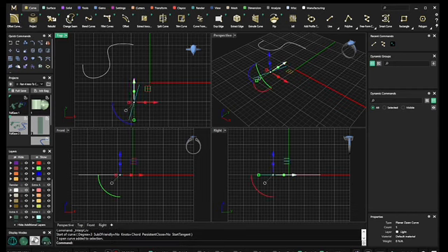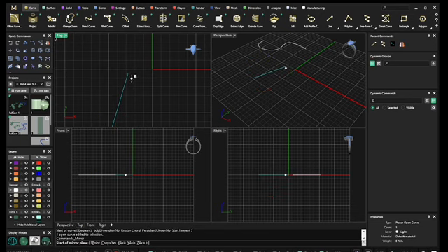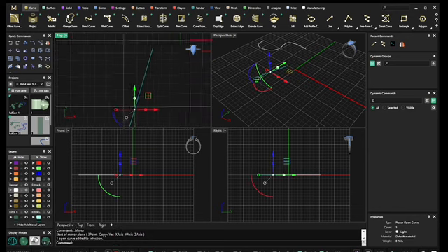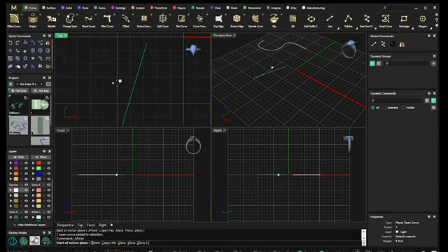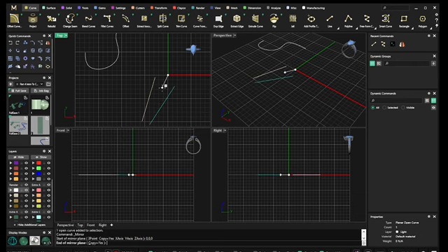And then record history. Let's use one of our little icons and commands from our quick command box called mirror. I'm going to select the line, go up to mirror, click on mirror. Then I want to follow what it says down in the start of the mirror plane, and that would be F4, because I want it centered on the center of my CAD universe, which is F4.